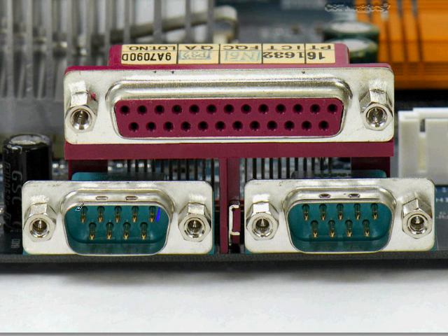Notice the D shell shape, remember it's a DB9, the D being a D shell. It's a little wider up at the top. And if you turn your head to the side and use your imagination, it looks a little bit like a D. That's pin 1. That's pin 2 right there. That's pin 3 right there. Pin 2 is normally used to receive data. Pin 3 is normally used to transmit data.